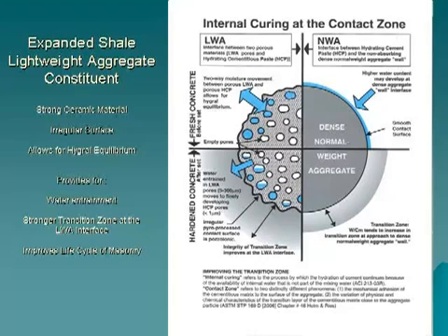Absorbed water within the lightweight aggregate improves the strength and impermeability of the concrete and has nothing to do with drying shrinkage potential. Just because lightweight block absorb more water, as we just discussed, does not mean they are more prone to shrinkage problems. It is important to understand that the water stored within the lightweight aggregate does not affect volume or expansion of the concrete or contribute to drying shrinkage.